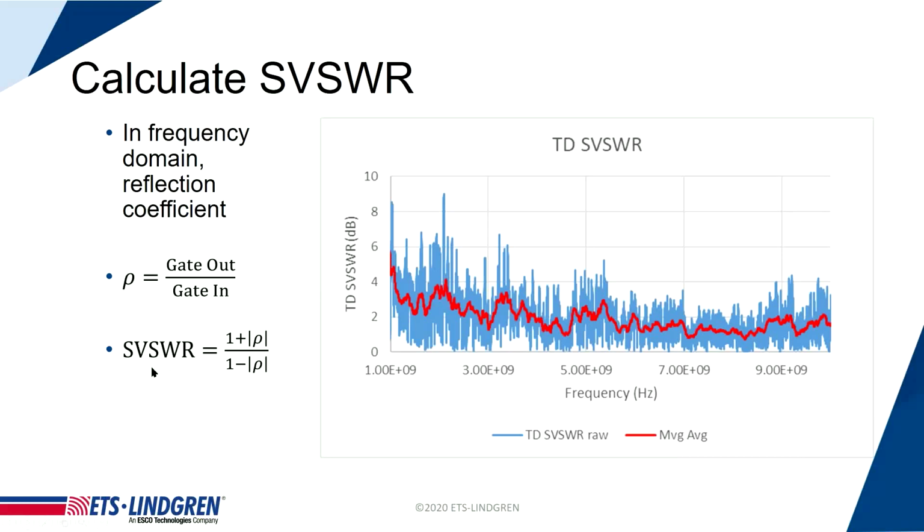Of course, in the VSWR method, all the standards and the metric are in VSWR. So this is a pretty easy conversion. We all know from our textbook the conversion between VSWR and reflection coefficient. This is the equation to convert the reflection coefficients back to VSWR. Here, the blue line represents the site VSWR calculated by this equation. I also drew a line that's a running average with a sliding frequency window, and if I take out all these rapid changes, this shows the overall trend.